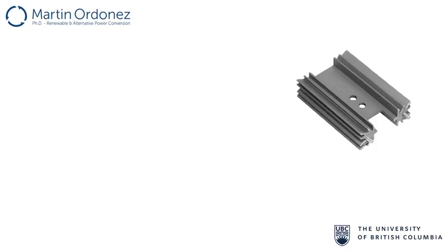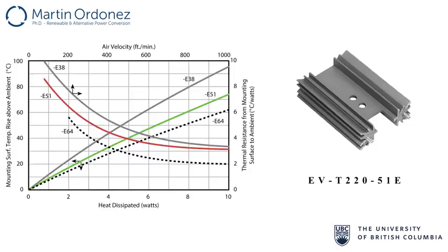In order to solve our problem, we need the datasheet of the heatsink. You can always Google the heatsink's part number and you can find its datasheet. There is a graph in the datasheet which shows heat dissipation characteristics. Now, you can see different curves in the graph, since we can select different heights for the heatsink. Let's try with the E51 that has a height of 51 mm.